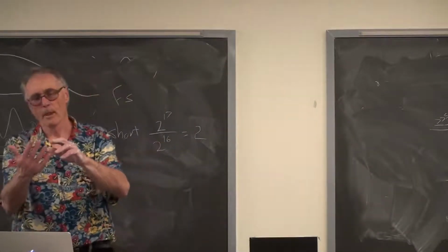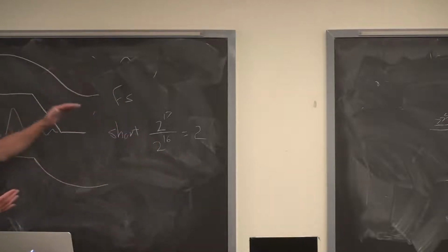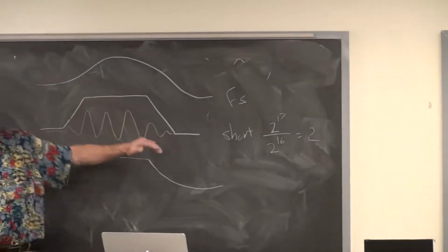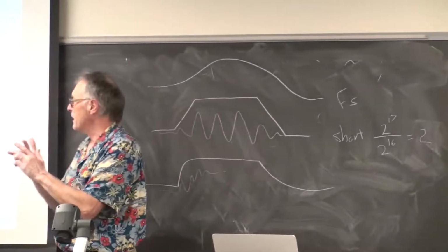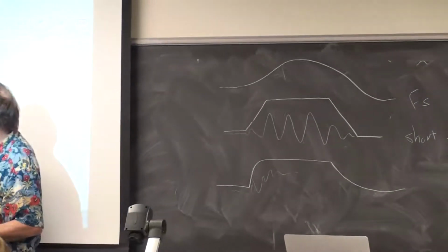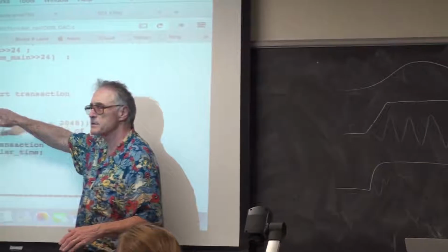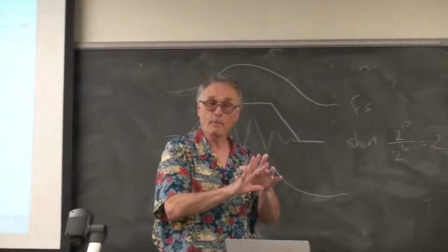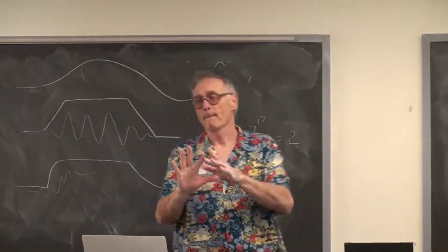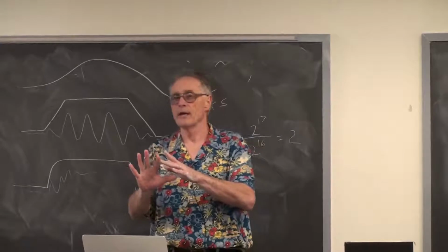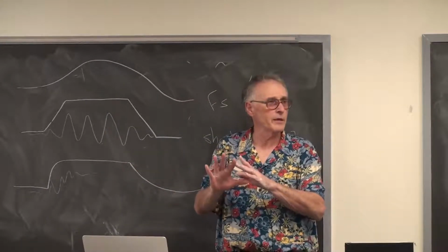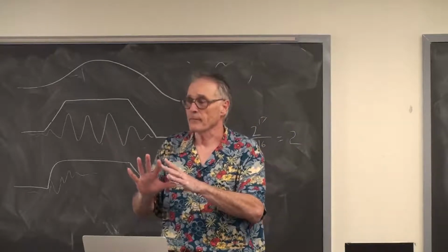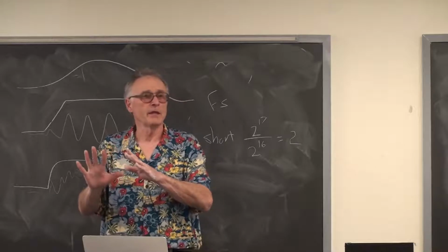So, direct digital synthesis, modulation of the sine wave by some function that you choose, probably linear, output to the DAC, which we haven't talked about yet, but these are serial peripheral interface commands. Output to the DAC, probably analog filtering, using a passive filter probably, although at least one person will probably build an active filter. And then speaker output.